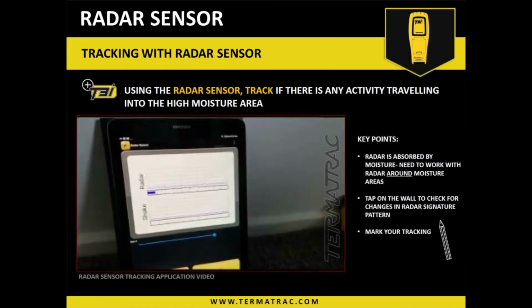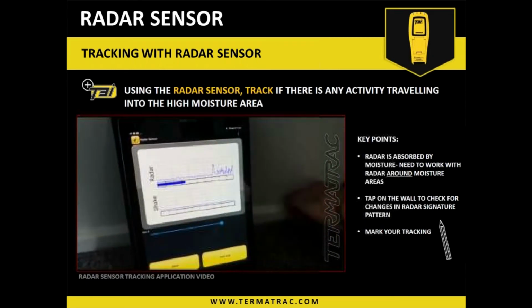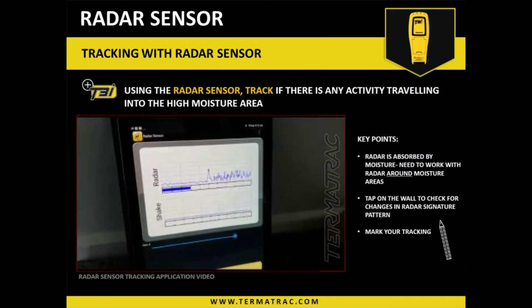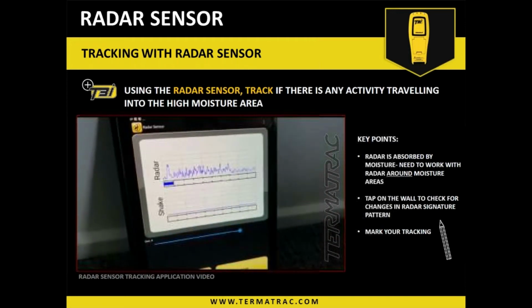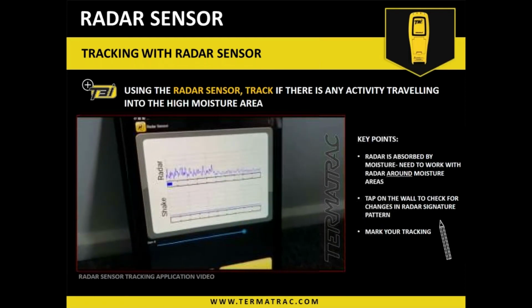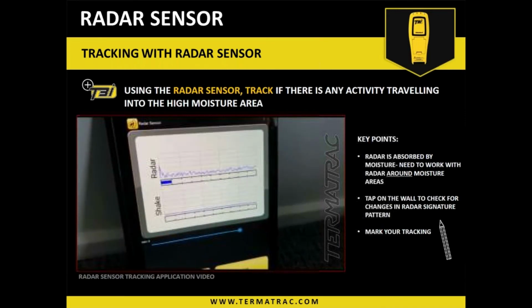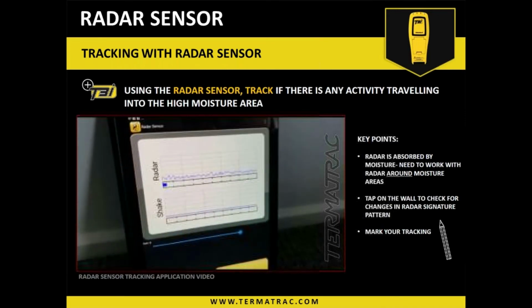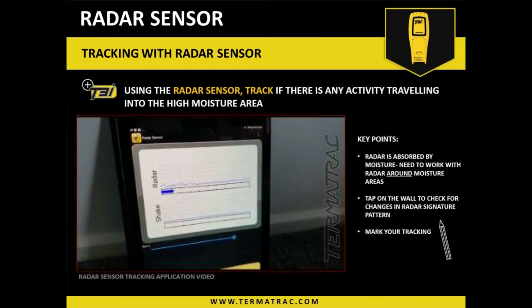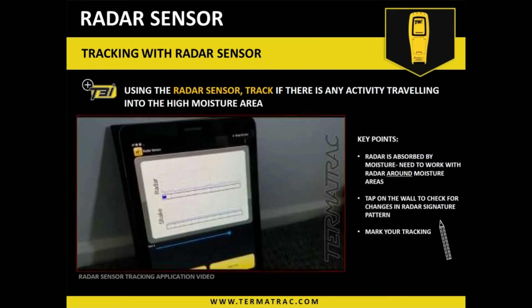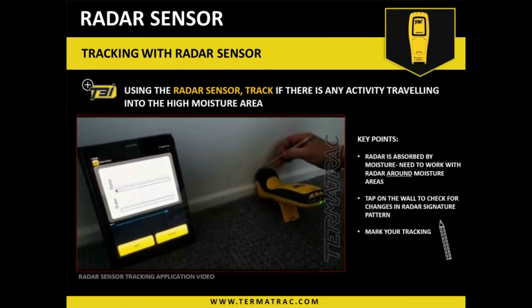What I'm going to do now, you'll hear this. So you'll see this intensified from me tapping. And we'll sit back and we'll watch what happens to our pattern. So what's happened, you'll see from where me hitting it, it's disappeared. Now the pattern has changed a little bit to when we initially put it there. So that's a good indicator. Termites are there. So what I'm going to do, this position, just pencil.